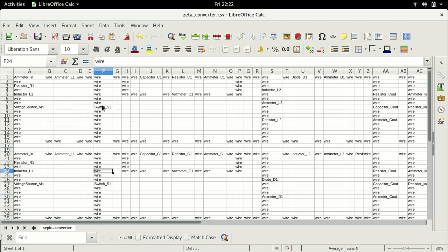So in the case of a ZETA converter, the first stage is similar to a buck. So what that means is the switch is moved out and comes in the series path. So let me just delete a few of these. The inductor comes here, right? This is the inductor. The switch now comes in the series path. This is the change of a ZETA converter.